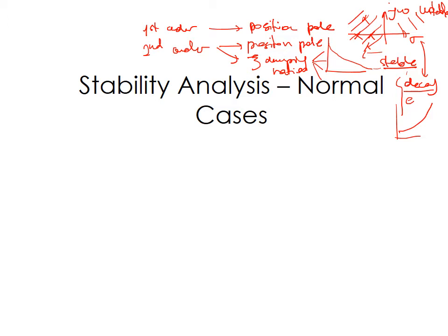If we have a damping ratio, for example, there are 4 cases of damping ratio, so I'll let you revise a bit. There are 3 cases of stable damping ratio, right? Where we have over damped, critically damped, or under damped. Whereas we only have the undamped case where it is not stable, yet it is also not unstable. So it is what we call marginally stable, right? So that's for first and second order.